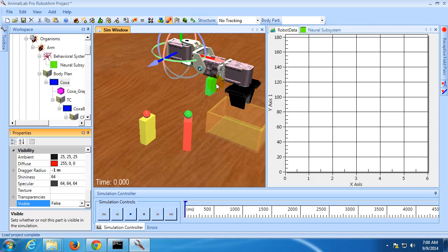They give you the ability to set a target position and a target velocity. You can set the angle limits, maximum torque, and a number of other key parameters for the motor. Even more importantly though, you can also query the motor to get back important data like its current actual position and speed, and its load, and whether any errors have occurred. This allows you to have a real sensor-motor feedback loop.